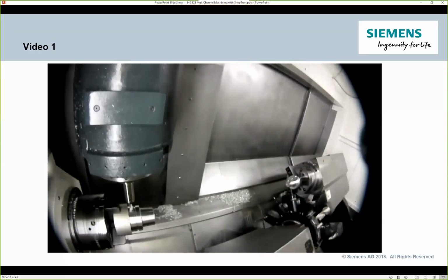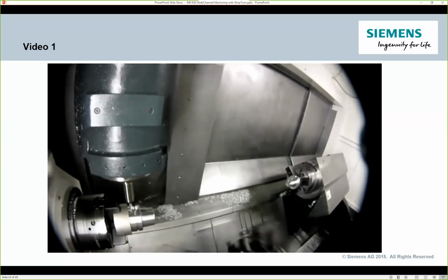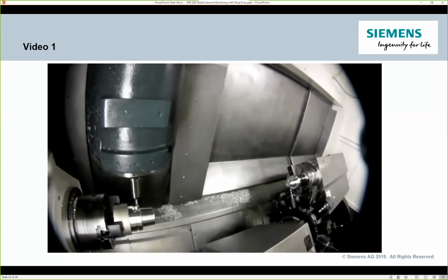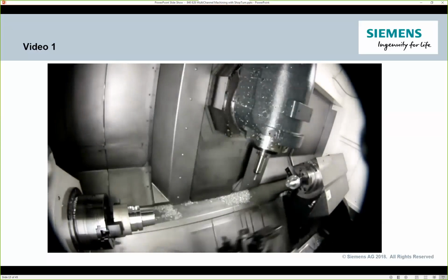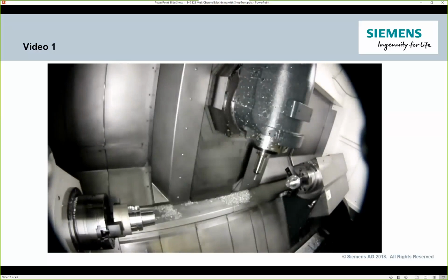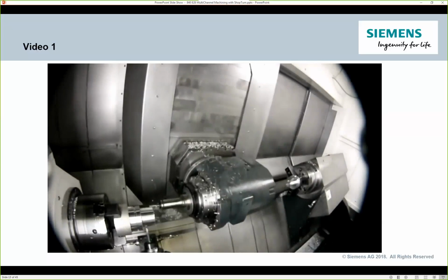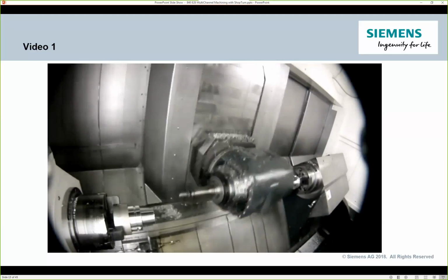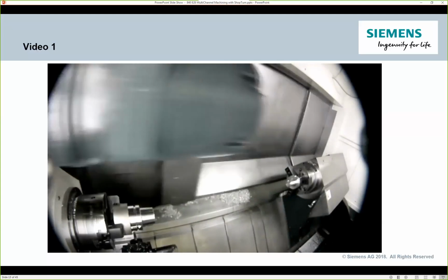So what you're seeing here, I would say this is probably usually your step one when you get into a multi-channel style machine, would be this upper turret, lower turret type of configuration, main spindle, sub-spindle. So the machine we're looking at here, this would be a two-channel machine. They may add a third channel to it for possibly work handling. That's pretty common, whether it's a robot or just like a little shuttle that can come over and pull parts out of the machine.